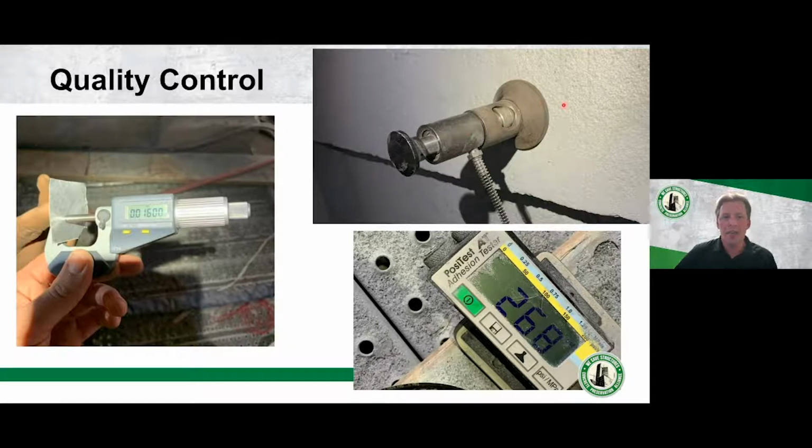Over here, once the zinc's installed, we do a bond pull-off test. And we want to see what the PSI is and how well that zinc has adhered to the concrete. We had a real good test on this one at 268 PSI.